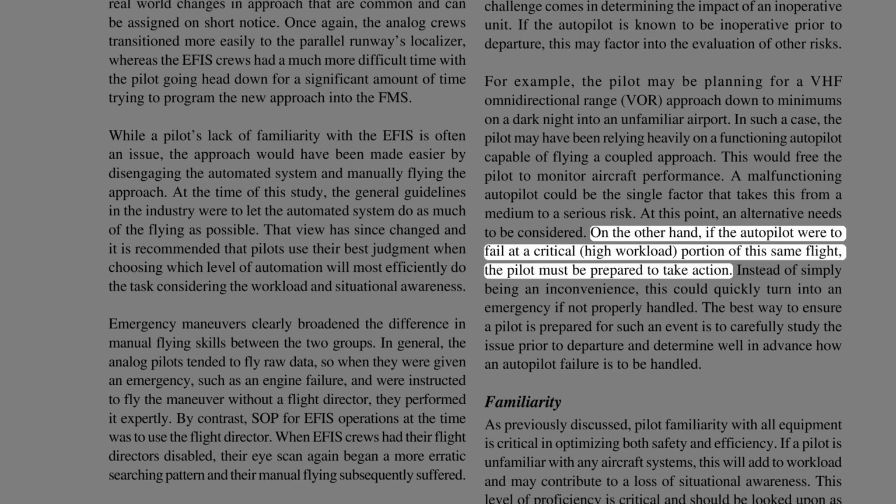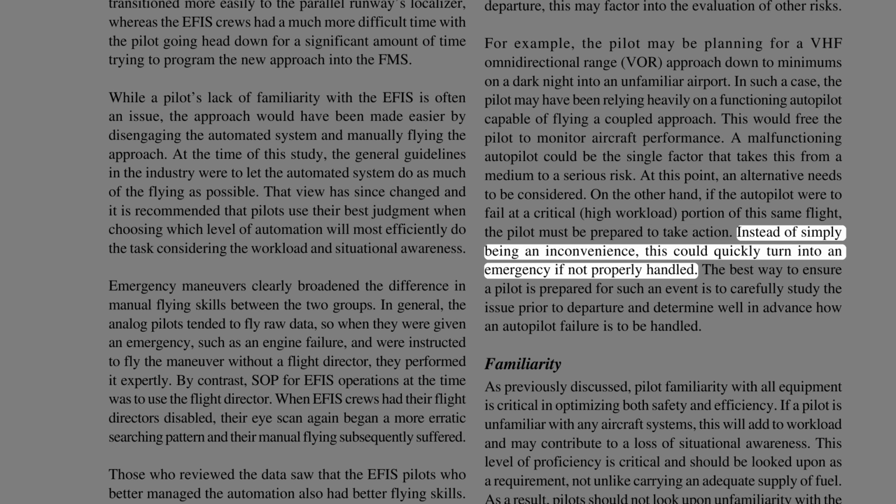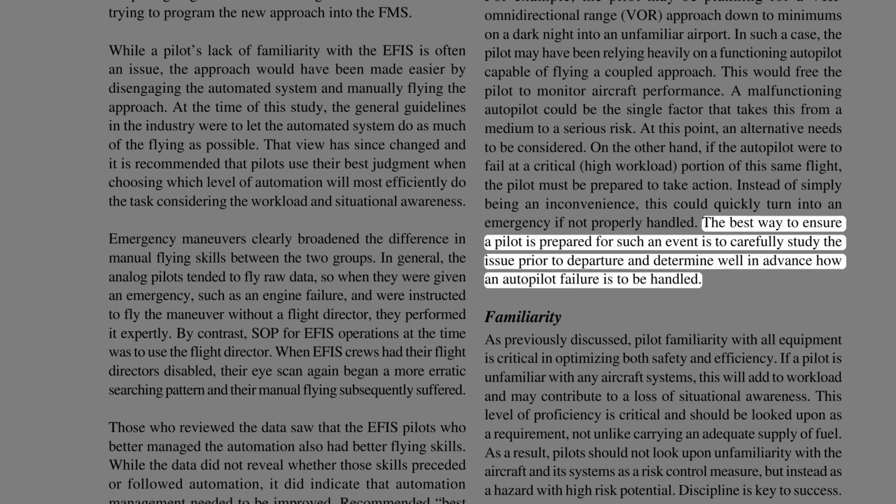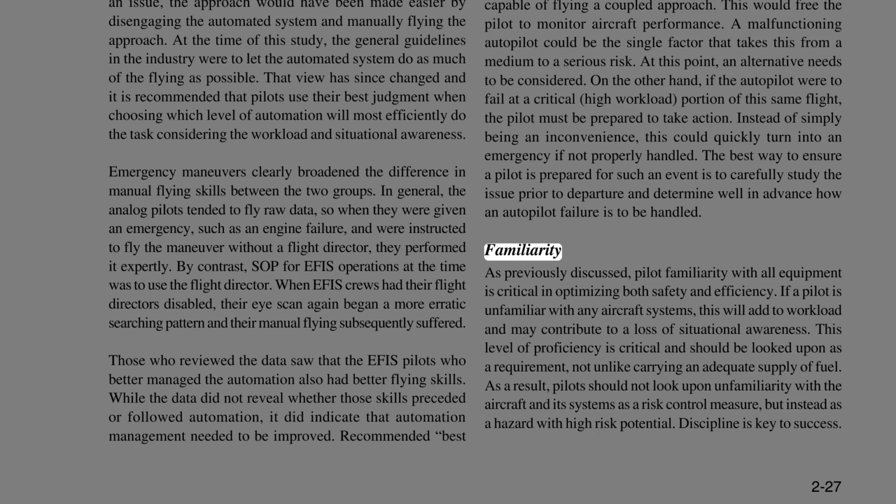On the other hand, if the autopilot were to fail at a critical high workload portion of this same flight, the pilot must be prepared to take action. Instead of simply being an inconvenience, this could quickly turn into an emergency if not properly handled. The best way to ensure a pilot is prepared for such an event is to carefully study the issue prior to departure and determine well in advance how an autopilot failure is to be handled.